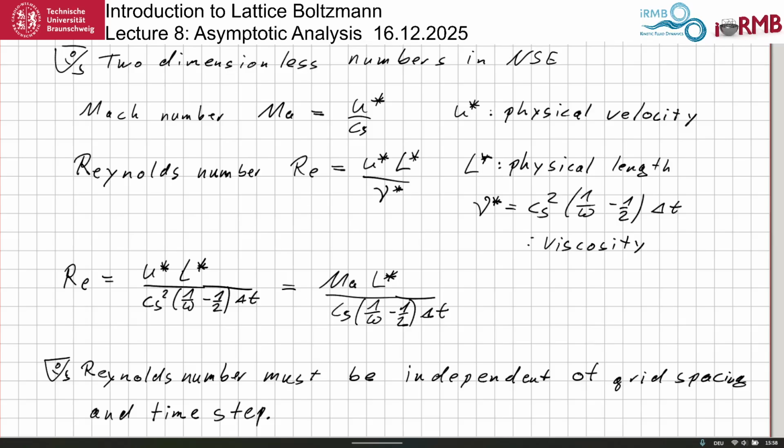The Chapman-Enskog expansion is different. It was invented to show the transition from the kinetic theory to the Euler equation, the Navier-Stokes equation, the Burnett equation, and so on. It is very often used also for the lattice Boltzmann method, but it's not actually derived for it, so you're misusing it a little bit.